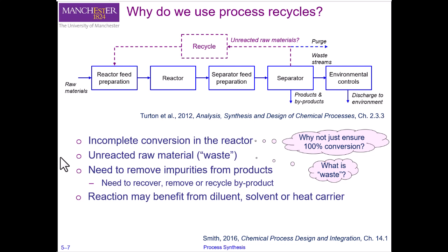purge for this purpose. Okay, but the purge may well also contain valuable raw materials or products, so it means that you are also losing your product with the impurity in purge. Clearly there is a tension here and a trade-off between recycling impurities and losing the valuable material and producing waste streams that do have some value.